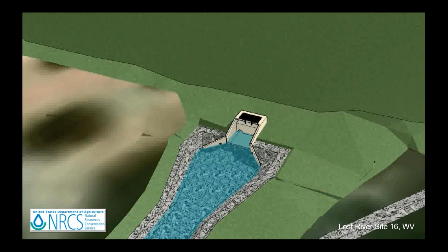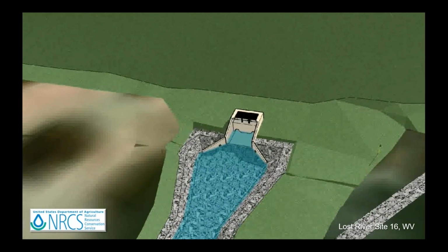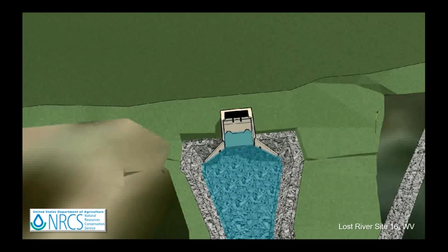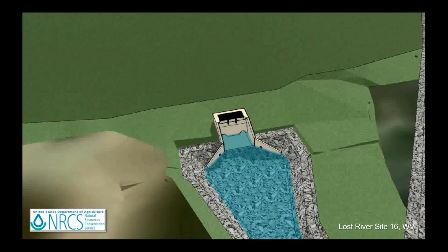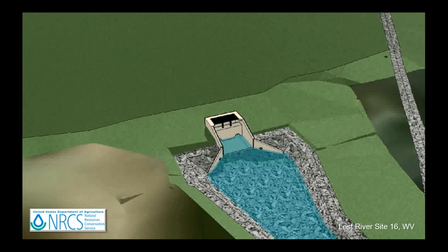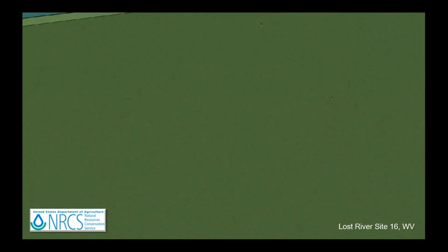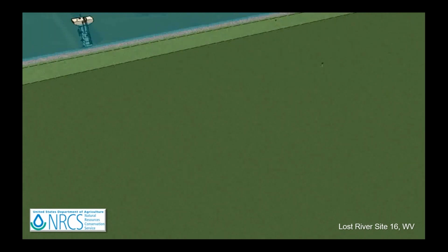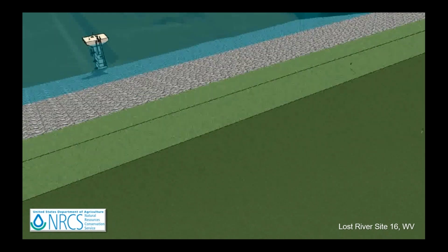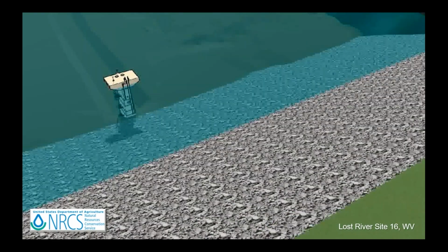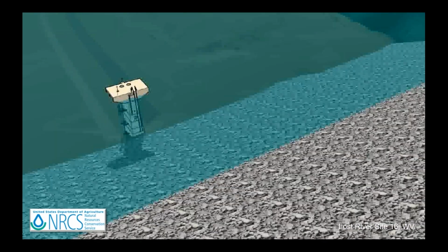We're going to go up over the embankment and look at, I can see the video is running a little bit slow here, so I think I might end up skipping over it. Oh, here we go. It's moving again. On the downstream slope, we have some instrumentation for high hazard dams. That's a common feature so that we can monitor the phreatic surface within the embankment.